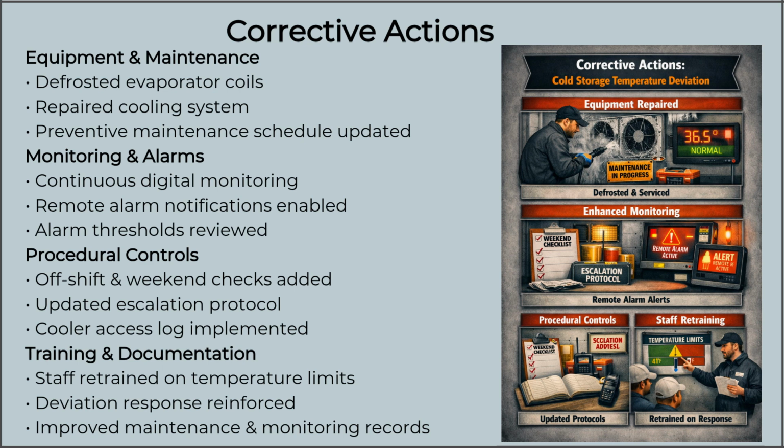3. Procedural controls. Added off-shift and weekend temperature checks to prevent long periods without oversight. Updated the escalation protocol to ensure immediate supervisor and QA notification. Implemented a cooler access log to track door openings and identify temperature-impacting behaviors.